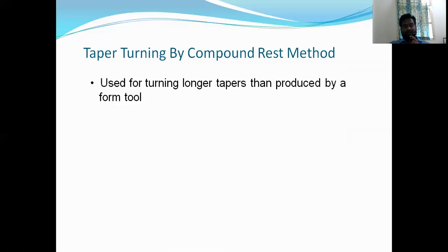Already I have told the drawback of the form tool method: the cutting tool has some width, and only that width shape is reproduced on the workpiece.